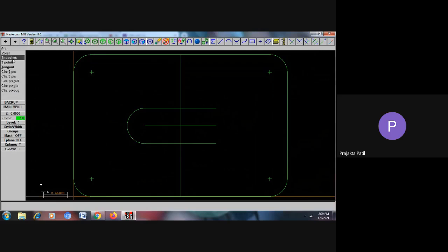Let us create an arc with endpoints. Which are those endpoints? One endpoint and other endpoint. And what is the radius of it? It is 0.5. We have got this. What region you want to keep? You click on that side, so it will remain. Say repaint. Okay. So I'll go to the main menu and I don't need this. This was just required so that the trimming is successful. I'll delete these lines. Now I don't need those lines, right? Next, now let me see what is remaining.